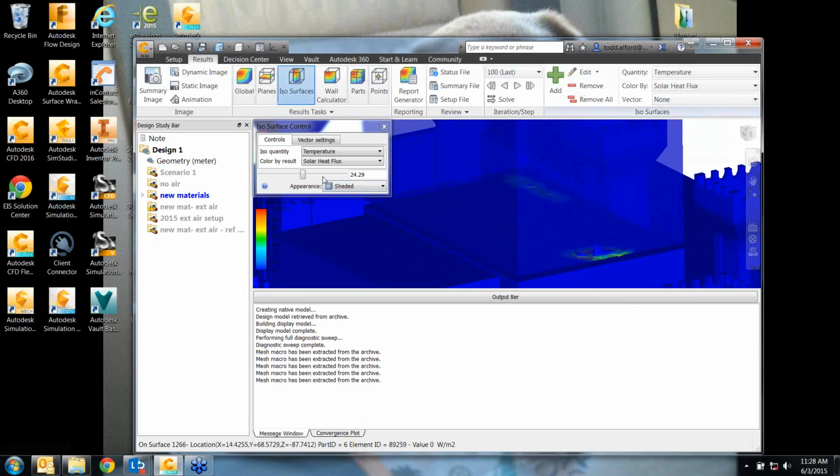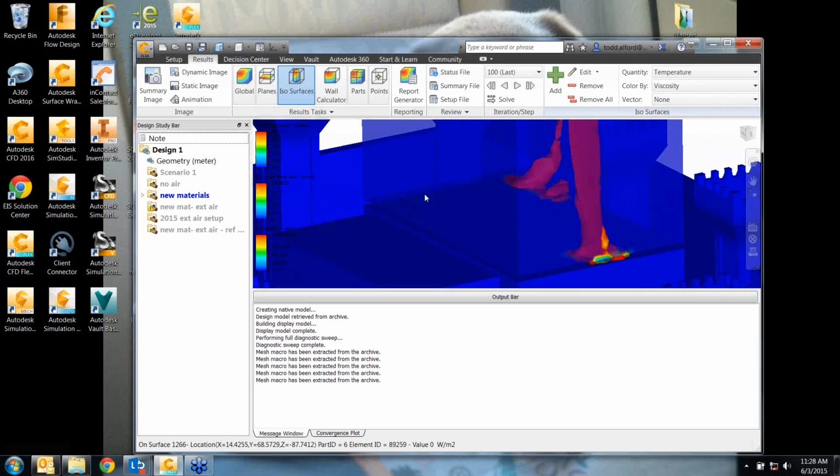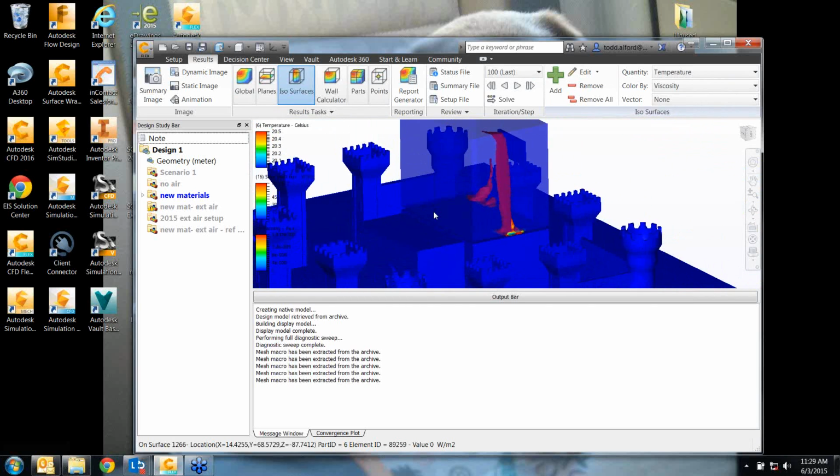So we'd have a solid inside. We could use a solar wall, that would be okay, using the U value of the combined 3 layers, or just calculate an average conductivity using the thicknesses, and then have a solar wall on the outside as well, so we could then take the solar heat gain coefficient to tweak the reflectivity. Then we could use a new model.